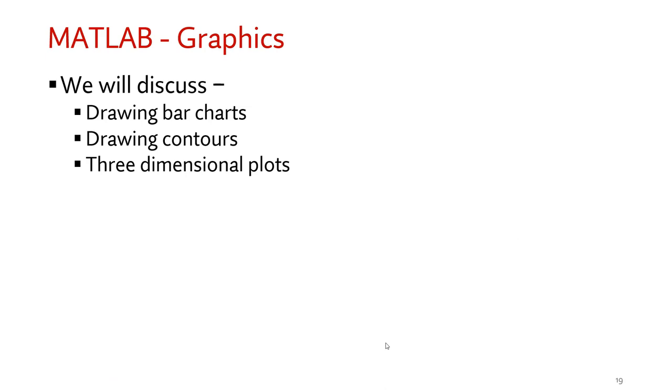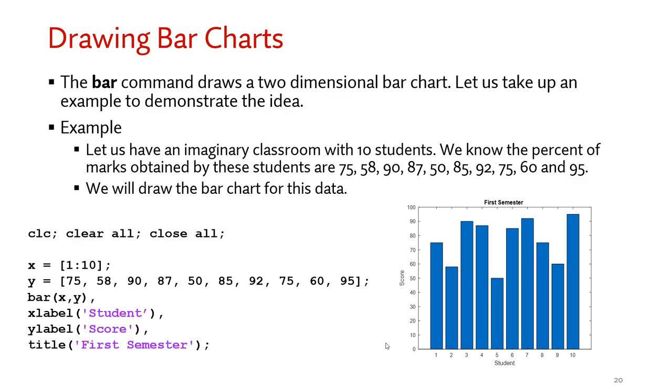You can also in MATLAB draw a bar chart or contour or 3-dimension plot. So you can use the command bar, and let's say this is student grades. So you can have the bar chart this way, and then you have the xlabel students, and the ylabel is score, and then you have the title as first semester. So this is also one of the nice features, the bar chart.